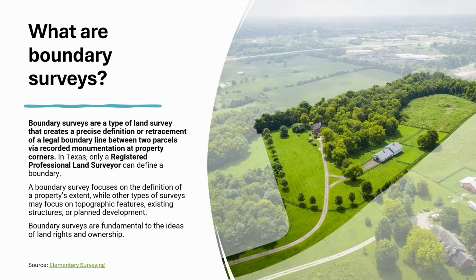All right, so what are boundary surveys? Boundary surveys are a type of land survey that's going to create precise definition or retracement of legal boundary lines between two parcels via recorded monumentation at our property corners. In Texas, only registered professional land surveyors can define a boundary. And that last part is really important, especially this being a mixed geospatial sciences program, that you understand boundaries truly, legally, can only be defined by an RPLS.